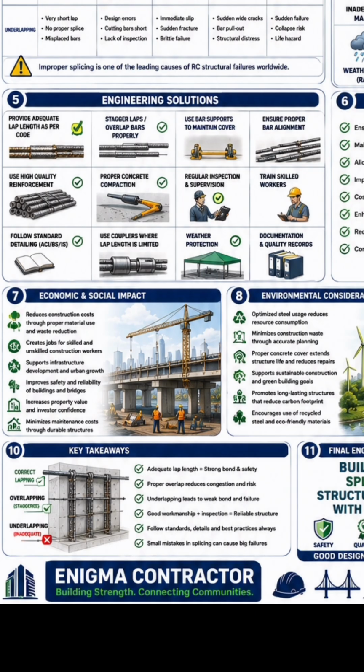Yeah, the next thing we have is an engineering solution. So for the engineering solution, which is number 5, we have the first one: provide adequate lap length as per code. So there are codes that actually teach, or explain, how you go about your lapping. So always ensure you follow the right engineering code for your lap length. If it is your beam, your column, your slab, your stand, so even in foundation, if you're considering lapping in foundation, there are codes you use.